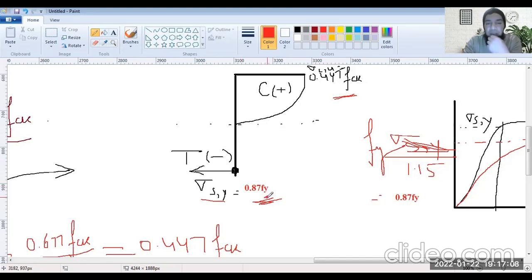The fy for steel would easily be 415 or 500 megapascals, and for concrete it is 2 megapascals in tension. So this is negligible. The role of concrete in taking the tensile load is almost negligible. So for the tension side, we do not take the stress envelope of concrete once the steel is there. We take the envelope of steel only.